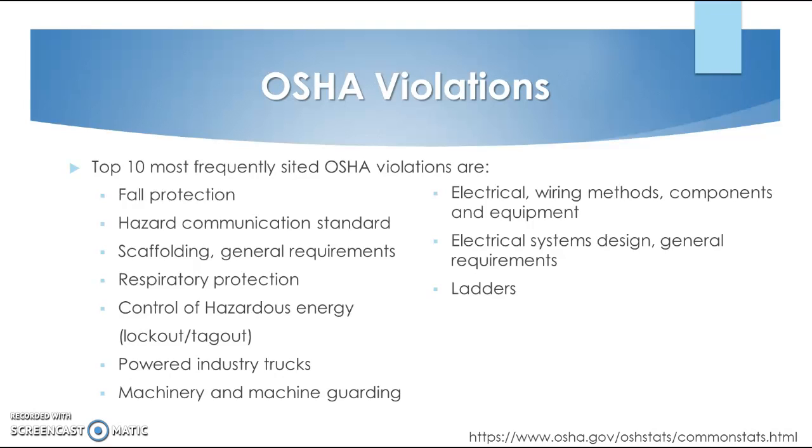Fixed ladders should be capable of supporting at least 2 loads of 250 pounds on each step. Therefore, when employers do not provide employees the appropriate ladders, or employees are using ladders inappropriately, the organization will be cited by OSHA.